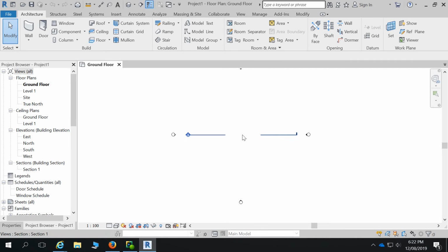So we're going to be looking at drawing some information into this middle of the window. Now remember in week 1 probably and week 2, I touched on this drawing area. North is always up by default, south is always down. So if you remember that, when you start drawing, you'll draw the northern face of your building up the top end and the southern face down to the south. Then you don't have to worry about halfway through your project trying to rotate it to orientate the building correctly.